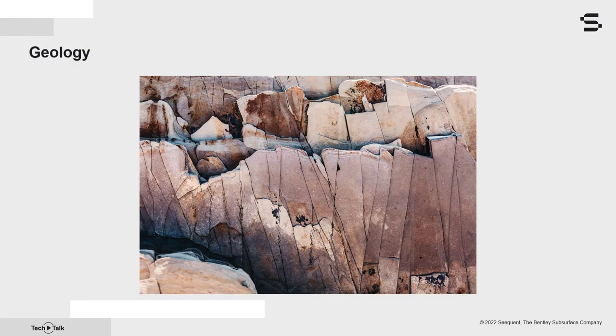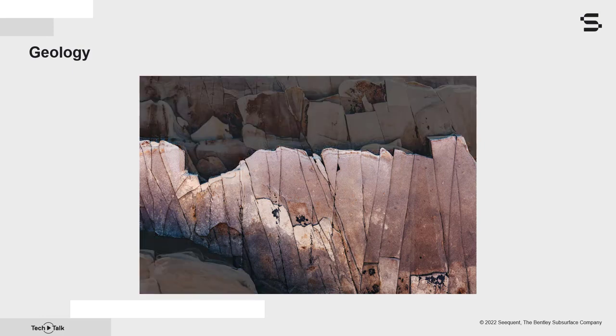To properly understand how the compound strength material model works in SLOPE/W, we need to make a brief detour into the world of geology. A rock mass such as this one includes many joint sets where the resistance will be lower than what is found within the intact rock mass. In the field, geologists will map these joint sets when characterizing the rock masses. For each joint set like this one, geologists will measure dip and dip direction, or alternatively the strike.